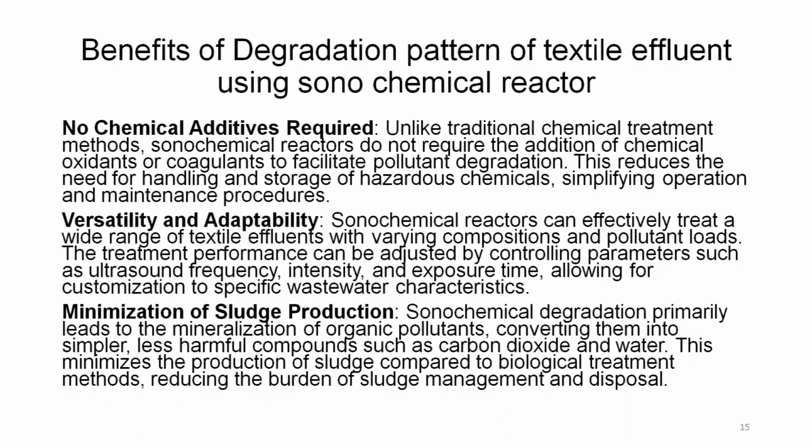Now, this is again a big advantage, that unlike traditional chemical treatment methods, where chemicals are dosed into it and then coagulation, flocculation takes place, Sonochemical reactors do not require the addition of chemical oxidants or coagulants to facilitate pollutant degradation. This reduces the need for handling and storage of hazardous chemicals and simplifies operation and maintenance procedures. So, definitely it has again one more feather to its cap.